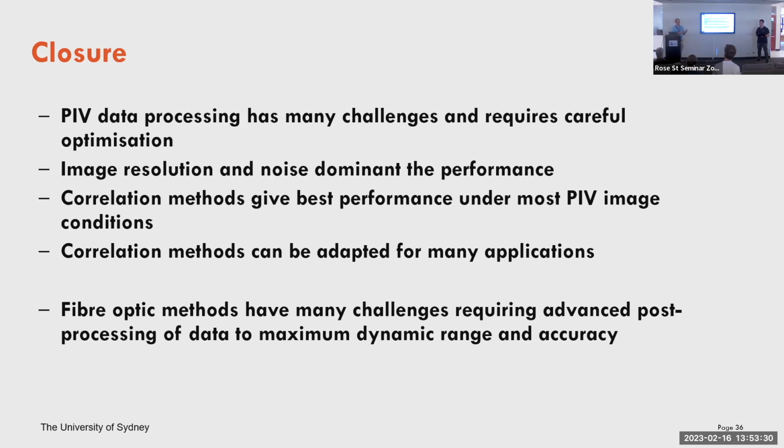So the sensor resolution is definitely driving the performance of where PIV is going. There are some odd little tweaks, like the peak fits get better and the number of bits in the image goes up, and that helps. But the old problem still seems to be there.